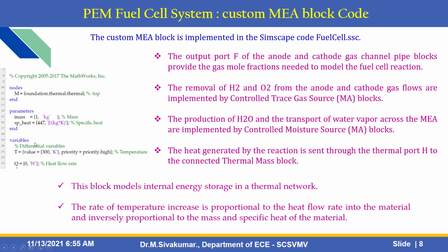The heat generated by the reaction is sent through the thermal port H and the connected thermal mass block. Here the rate of temperature increase is proportional to the heat flow rate into the material and inversely proportional to the mass and specific heat of the material.